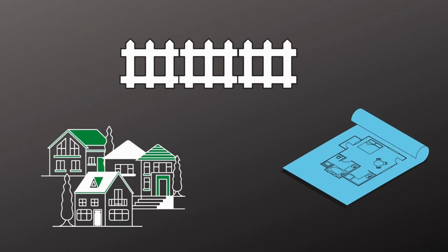At the same time, the architect moves the process forward and works on step number 7, that's the site plan. For the site plan, the architect checks the zoning bylaw and provides the setbacks from the property line. At this point, you can decide the proper location of the building as per the city rules and regulations.